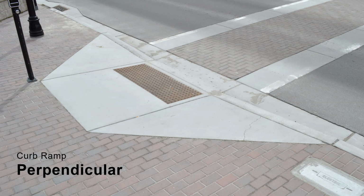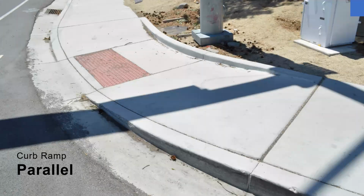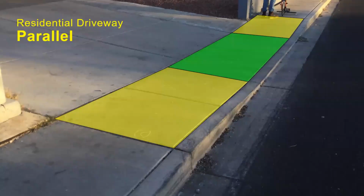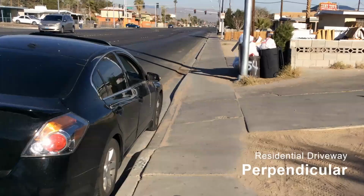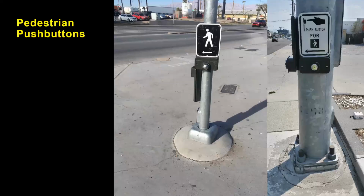Curb ramps vary in design, requiring manual evaluation of the type of curb ramp and the applicable design specifications. Residential driveways can function somewhat like the curb ramp, lowering pedestrians to the street level as the pedestrian access route crosses the driveway. Older designs force pedestrians across difficult cross slopes, while better setback designs keep the access route level with the sidewalk. Pedestrian push buttons are also necessary to not only assist pedestrians in alerting the crossing signal, but also in directing pedestrians with vision impairment to the opposite side of the crossing.